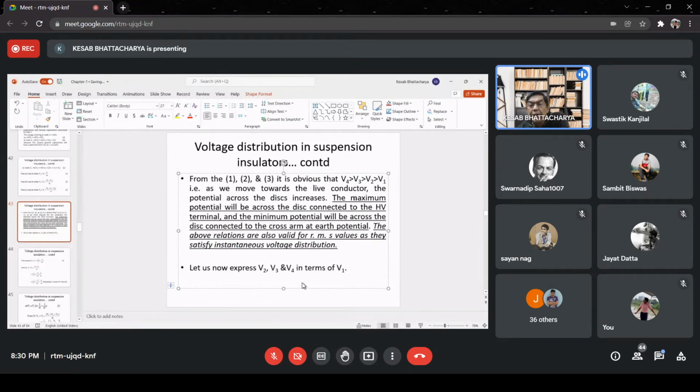So these 2 points, I think you well understand. Do you understand, or do you have any question about these points? That is the distribution of the voltages. Minimum voltage will occur across the disc connected to the tower cross arm directly, and the maximum voltage will appear across the disc connected to the live conductor directly. Do you understand this point or not?